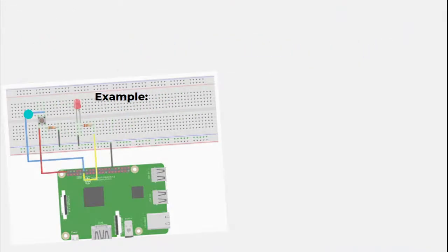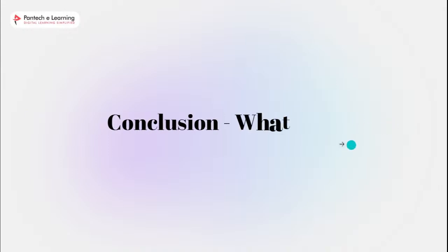Okay, so the last thing, which is the conclusion. Each GPIO on the Raspberry Pi has a 50k ohm internal resistor, which can be used as a pull up or pull down resistor in your program. By default, before you set anything, the resistor for GPIOs up to number 8 will automatically be set at pull up, and for GPIOs after number 9, pull down.